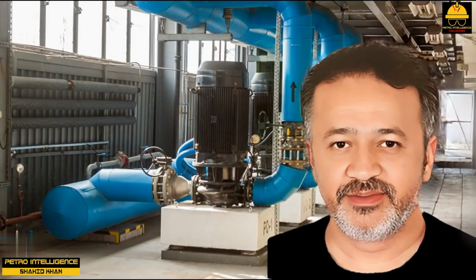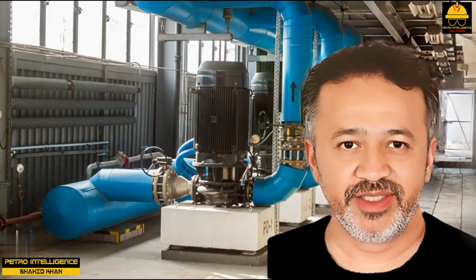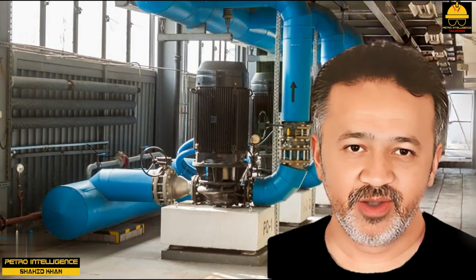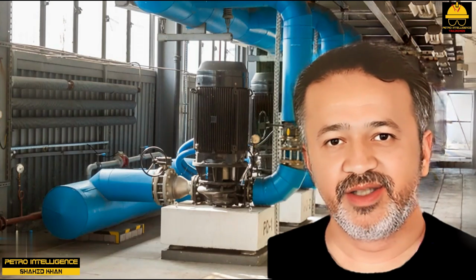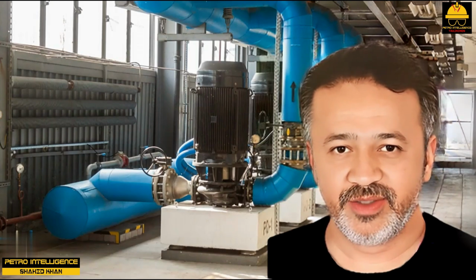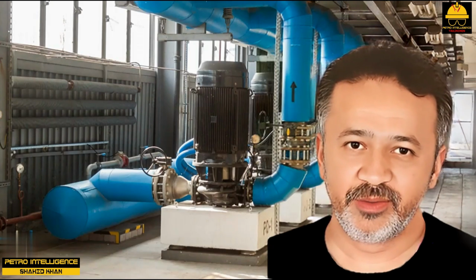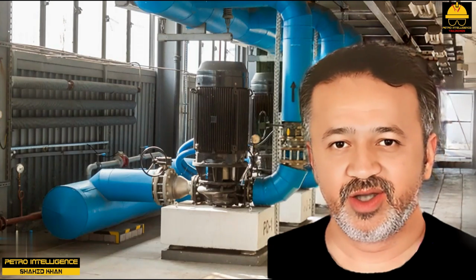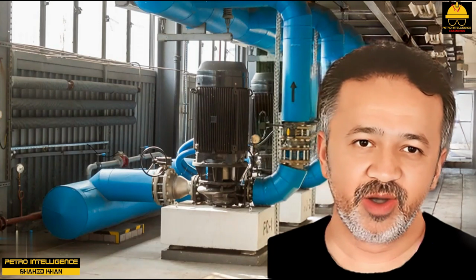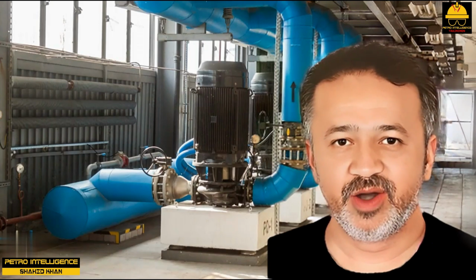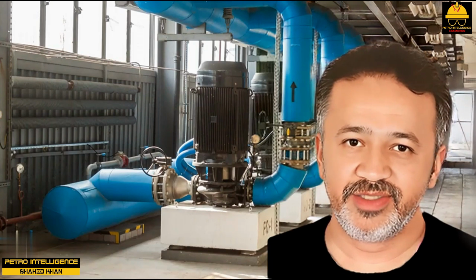Impeller diameter. The pump impeller resembles a hollow wheel with radial vanes. The diameter of this wheel can be trimmed down on a lathe. If an impeller with a 10-inch diameter is trimmed down to 9 inches, it will have a new performance curve below its former performance curve. Both the flow and head of the pump will be reduced. Also, the amp load on the motor driver will decrease.